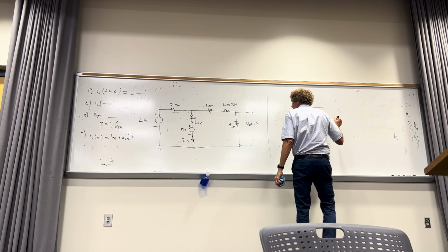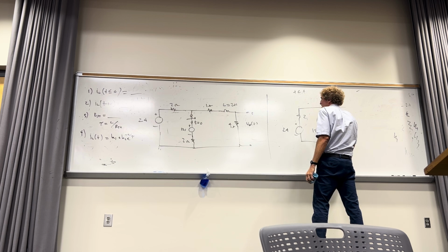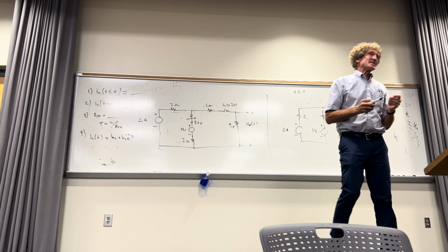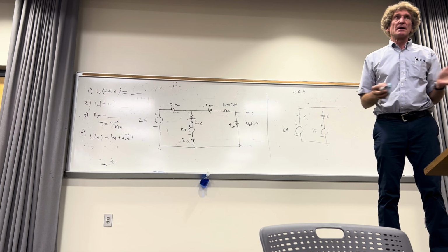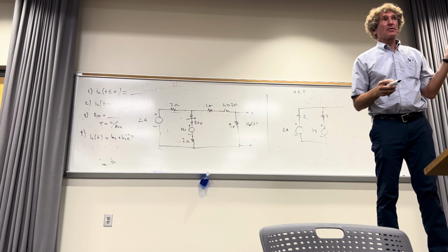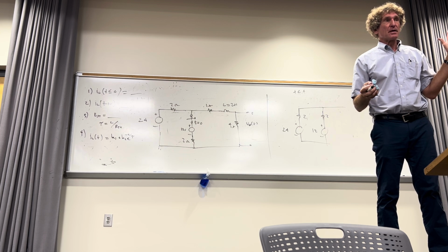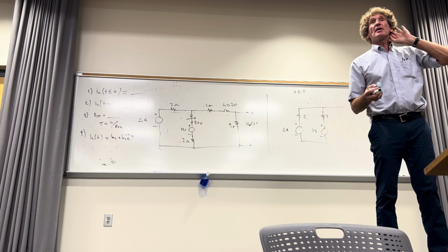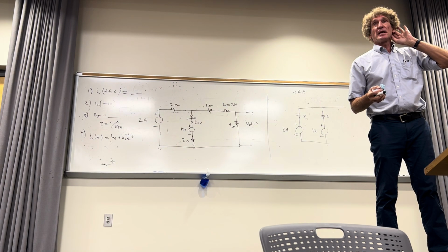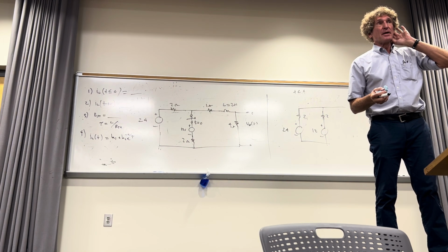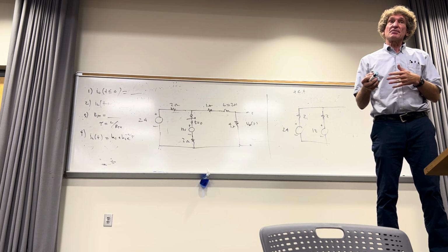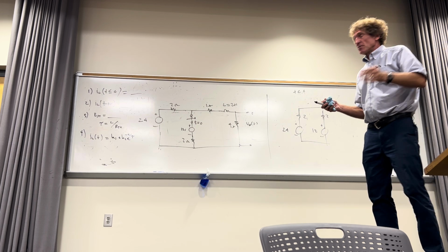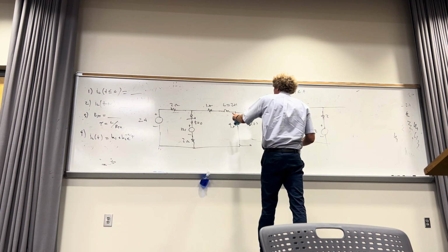And then finally, over here, what does the inductor look like? What do you represent it as for t less than 0? Anyone? Short circuit. All right, you've got to speak up. Did y'all hear that, class? That's all it is. If there's nothing changing with time, and there isn't, because for t less than 0 you can assume it's been on forever, since the beginning of time, you can just put a short circuit there, and that's the current I want.